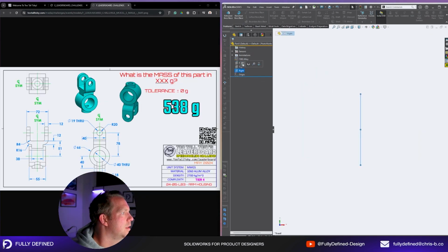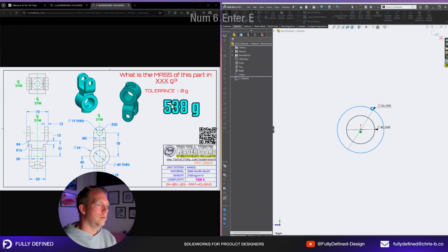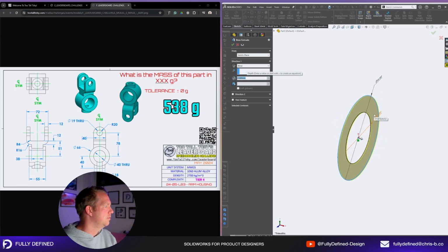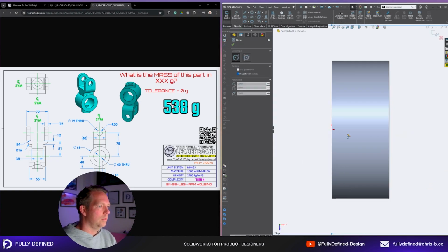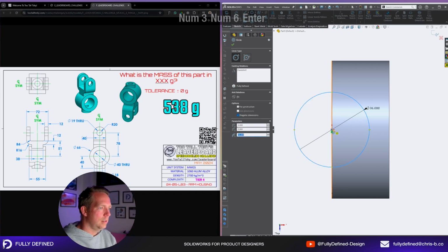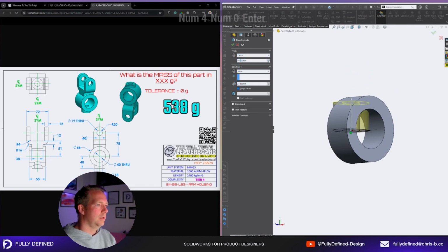Let's start on the side view, right view. We're doing this shape first, 40 and 66. And we're going to extrude one direction and we're going to go halfway, which is 55 divided by 2. We're going to go on the top and we'll do another hole. This will be the 36 and the 18. Now this is one we might want to change. Comes down 40 and it's going up to next. So going down 40,